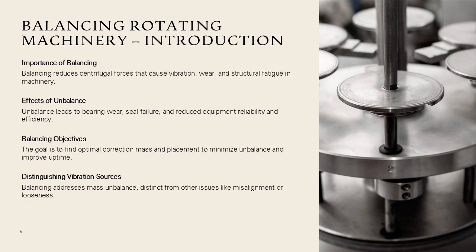Unbalance produces centrifugal forces proportional to the square of rotational speed, leading to elevated vibration, bearing wear, seal failure, structural fatigue, and reduced equipment reliability. The introduction emphasizes that balance quality affects operational efficiency, energy consumption, and machine uptime.